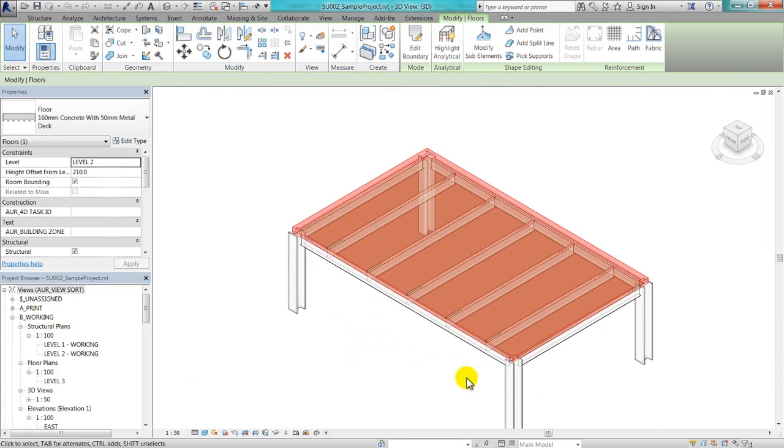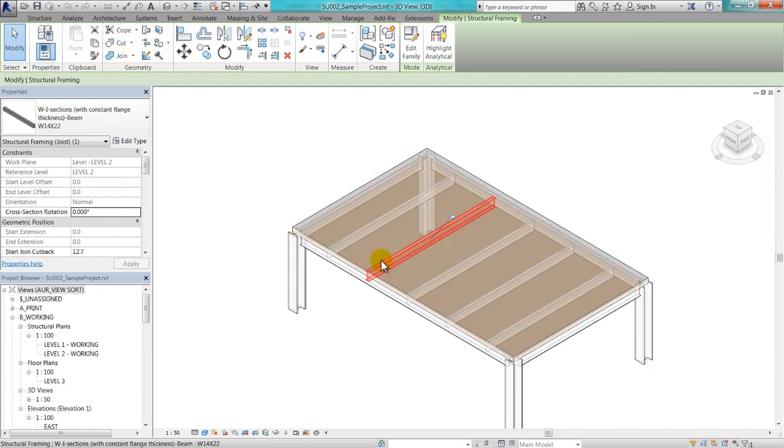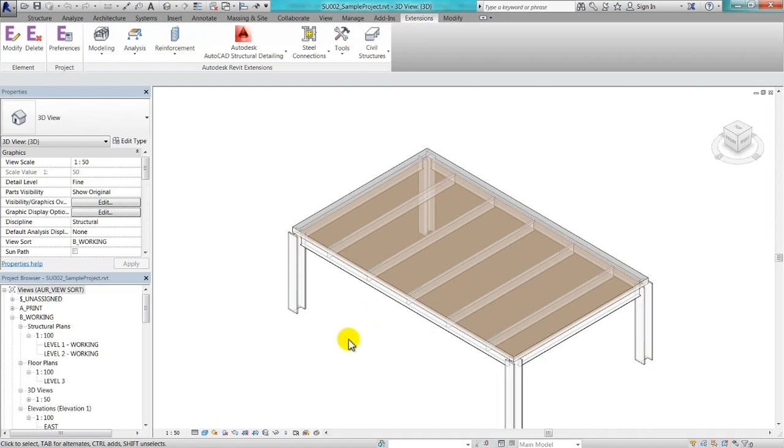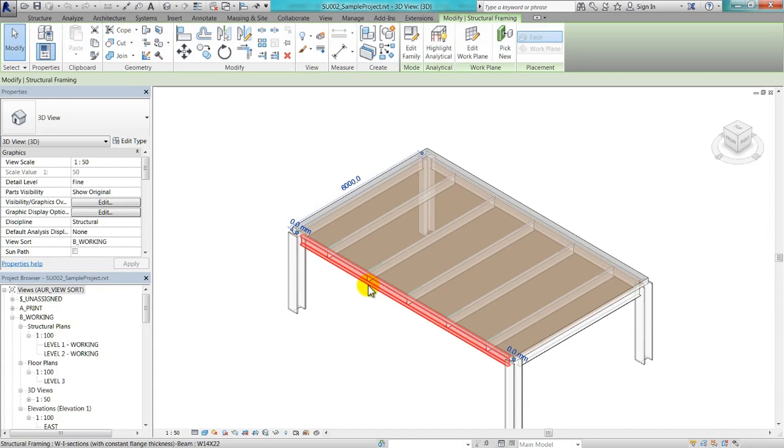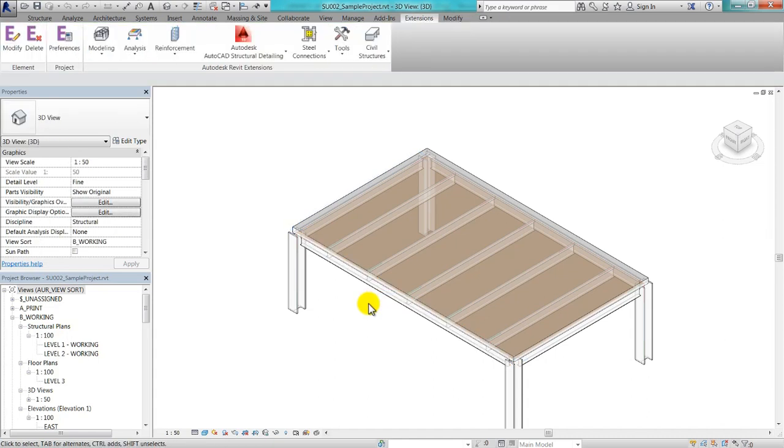Also, as per the AISC design guide, the tool assumes that beams will act in composite action under service loads. Uniform floor loading is assumed; point loads, etc. are not incorporated. Beams must be supported by girders. Walls as supports are not allowed. At the same time, supporting beams and girders must be wide flanged beams according to AISC standard. Non-conforming beams will simply be ignored.